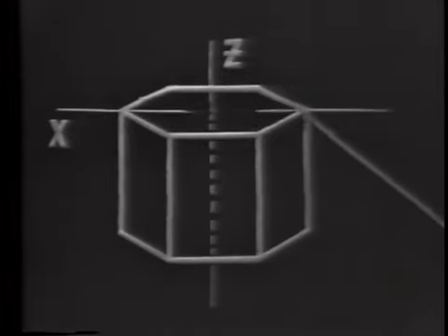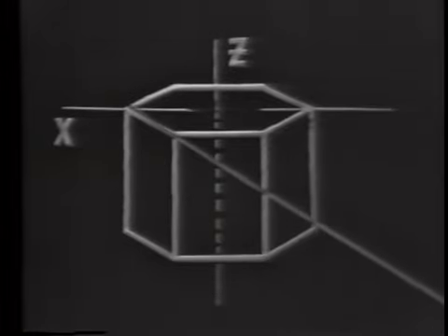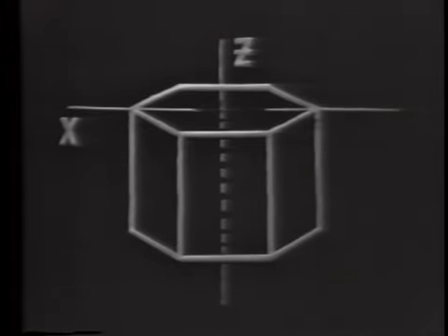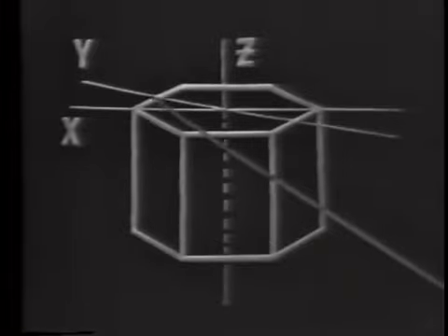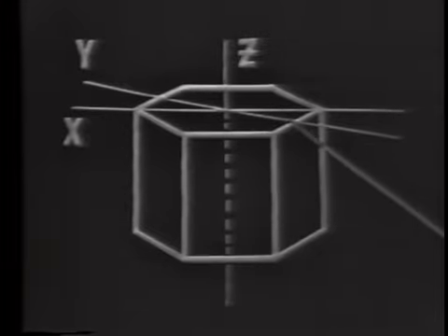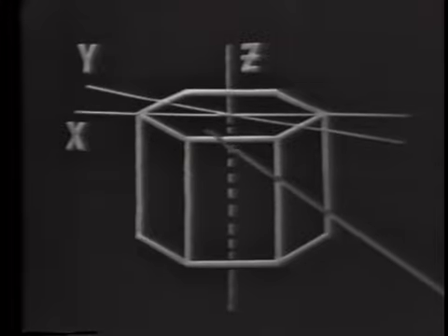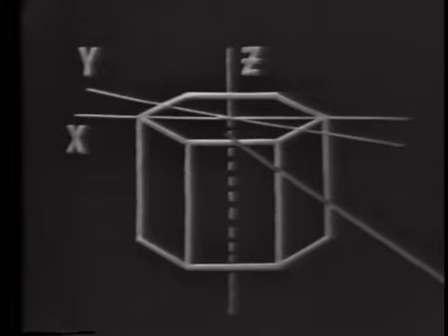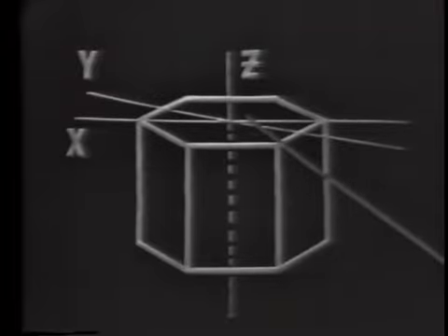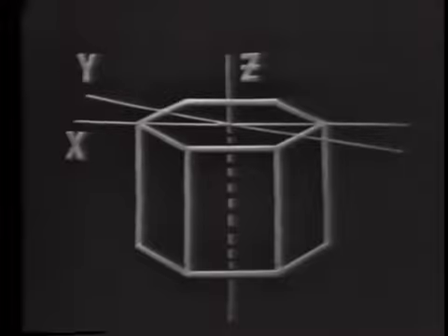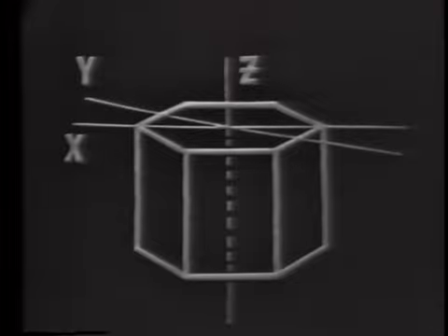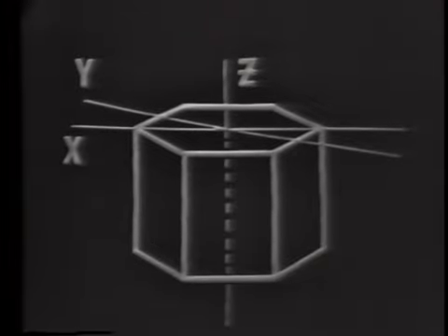The axis passing through the corners of the crystals is known as the x-axis. Remember, it goes through the corners. While the axis perpendicular to the faces of the crystal is known as the y-axis, going through the faces. Let's remember these are only imaginary lines and are used as reference points when cutting the crystal. At this time, complete item 3 in your TVI guide by labeling the axes there.